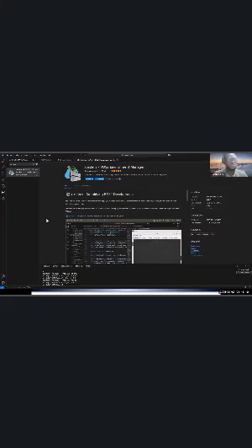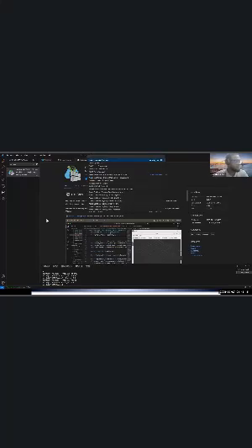So all you need to do now, for anyone that also has ROS2 installed, that means you'll be testing what we're doing today as well. Just do Control Shift P. Are you able to do that? You can create an environment. Can you see it? When you create the environment, you can click Humble. Once you click Humble, it creates a Humble environment, but you need a stable internet connection to containerize the package.